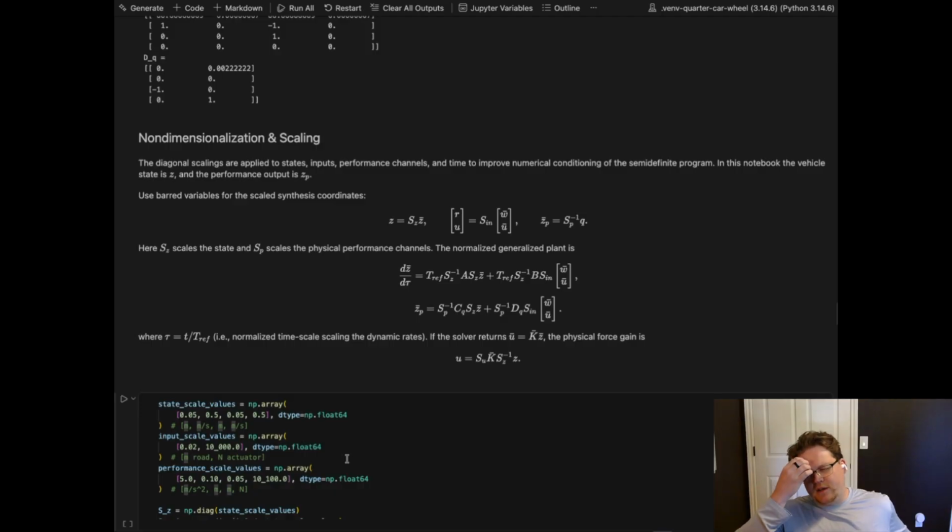The one thing that will show up, if you don't do this in the H infinity control, is you could get into a scenario where I'm going to show the H infinity norm metric actually being violated if you lessen the tolerance too much. And it's going to be proportional to the factor by which you lessen the tolerance. So that is one thing to be careful of. But anyways, let's step into this part.